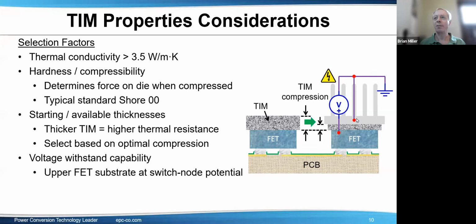Another point that I should have made in the previous slide is it shows a heatsink here, but instead of a heatsink, this could also be the chassis of a device. If you have a metal chassis and the metal chassis is bolted to something else or it works well to dissipate heat, instead of an aluminum heatsink, you can have an aluminum plate, or say, a steel case. The concept is all the same: getting the heat from the FET through a thermal interface material to something else, and having a spacer to maintain a good gap between the board and the top of the metal right here.